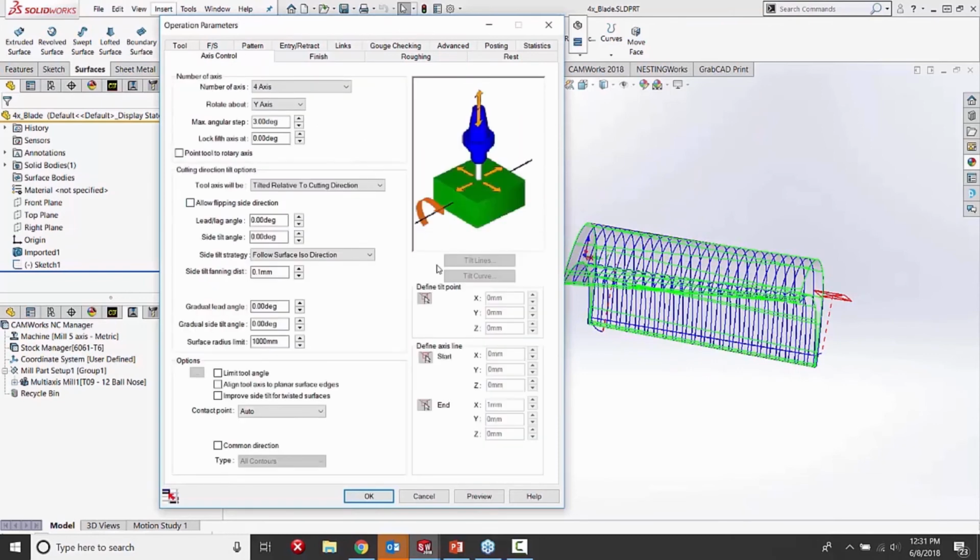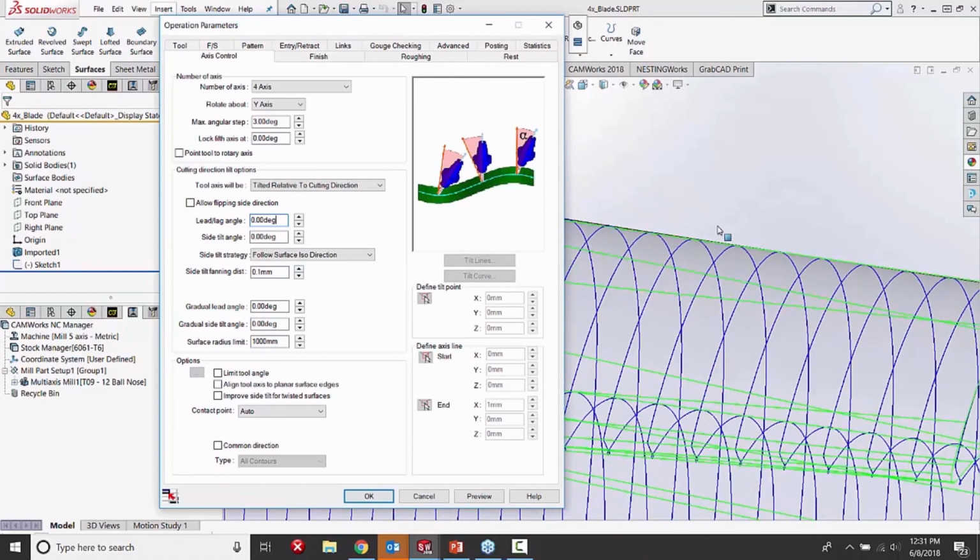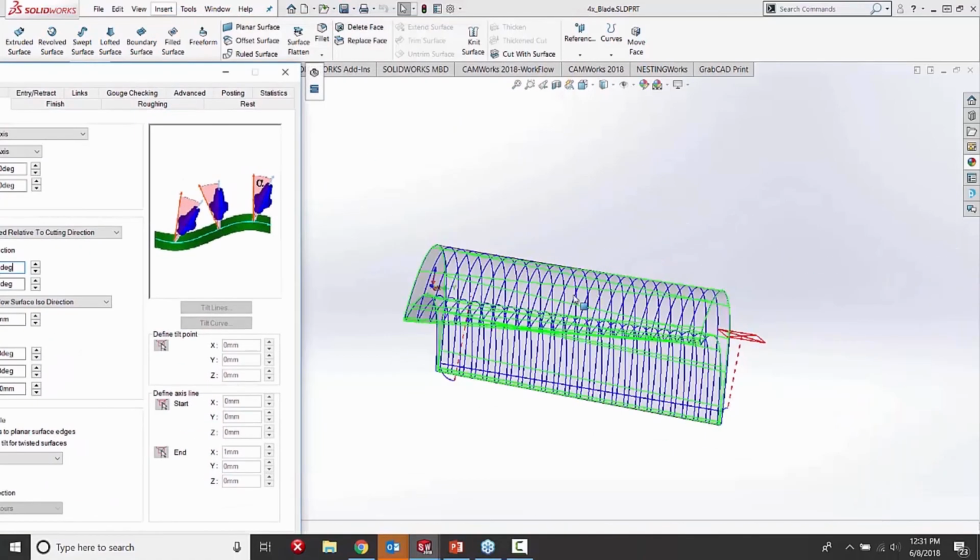Last idea here with finishing and ball nose end mills is we typically don't want bottom dead center of a ball nose end mill to be doing the cutting action or be what's driven on the part. And that's what's happening right now. This line is literally the end point of this ball end mill, bottom dead center, which if you're a machinist you know doesn't have any speed on it. Right at the middle of the tool, there's no cutting edges, there's no cutting speed.